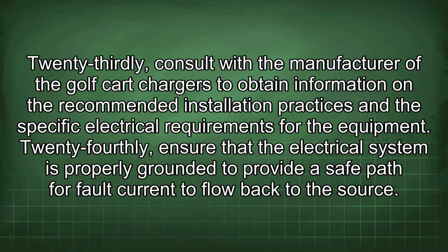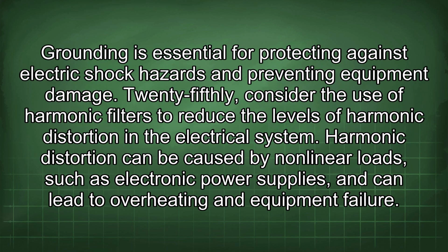24thly, ensure that the electrical system is properly grounded to provide a safe path for fault current to flow back to the source. Grounding is essential for protecting against electric shock hazards and preventing equipment damage.